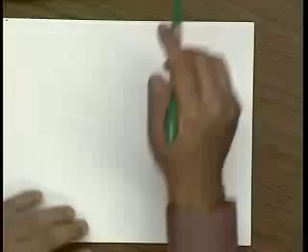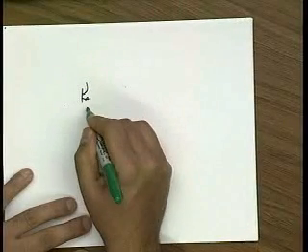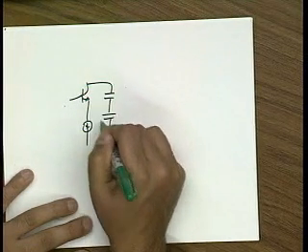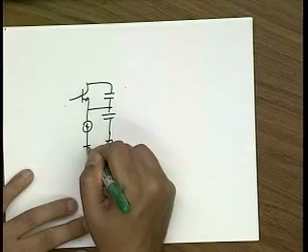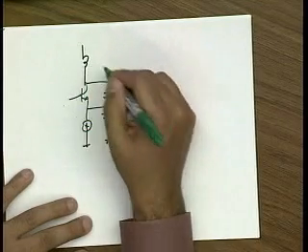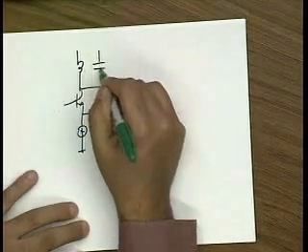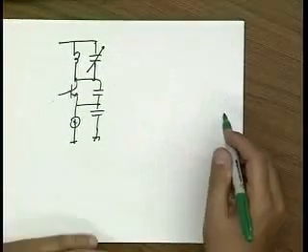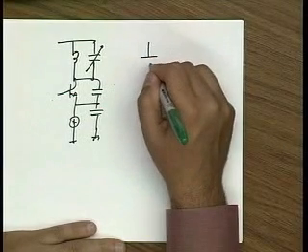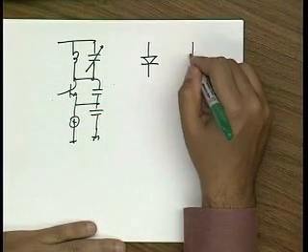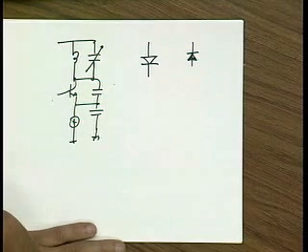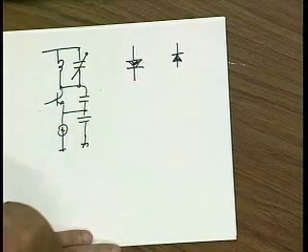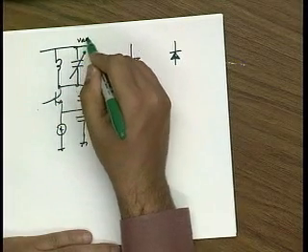So for instance, if I go back to, let's say, my Colpitts oscillator, this is going to be some fixed capacitance. I'm going to have my inductor, and then now I need to introduce my variable capacitance across here. Okay? And so now I have a choice. I can hook this up in several different ways. I could hook it up like this. I can hook it up like this. Right? So keep in mind, I want this to be reverse biased. So this point is at VDD.